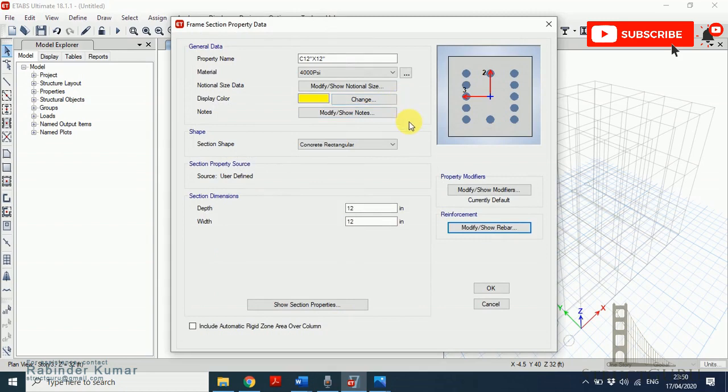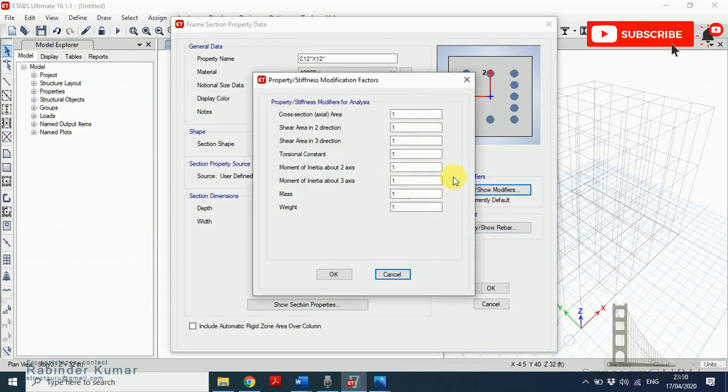Now we have to define a column modifier. Let me go with show modifiers. As we are using the ACI 318-14 code, in this code we have to change these values. I will explain the purpose of changing these values at the end of my video. For the torsional constant, the code recommends the value of 0.01.